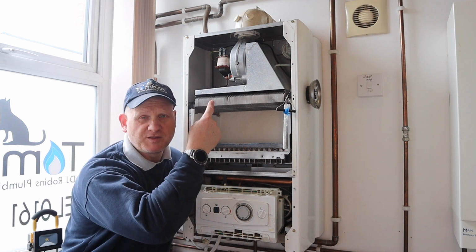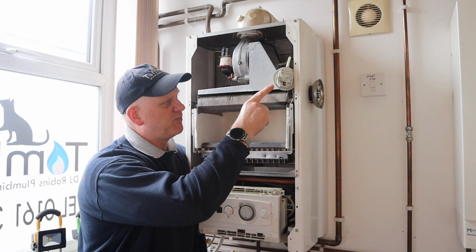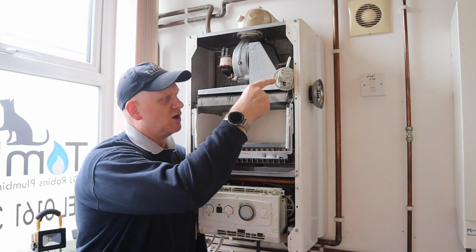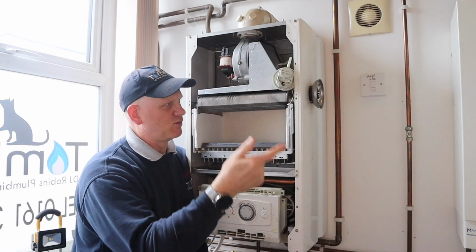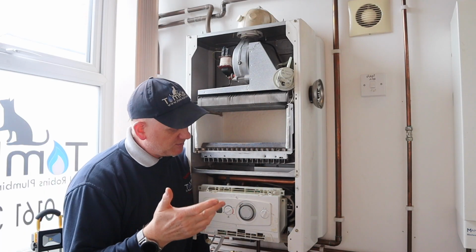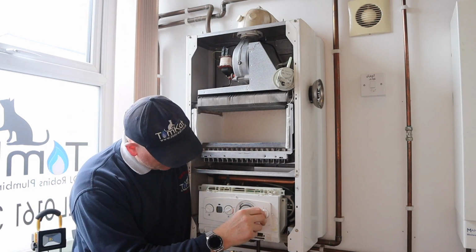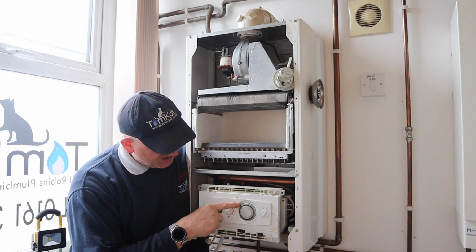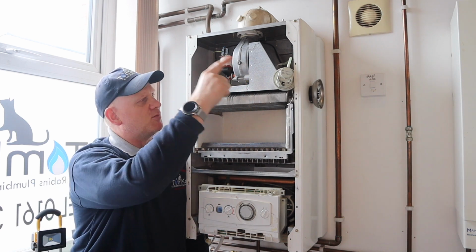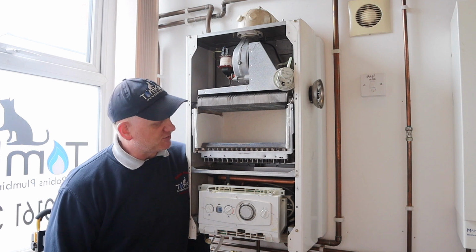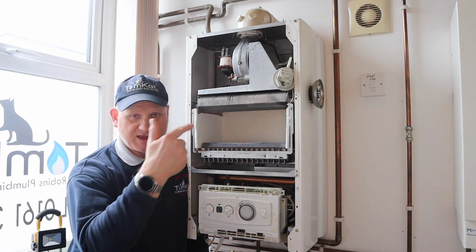So, let's see what other things we can do with the air pressure switch then. Now, this time what I've done is I've plugged one of the cables onto the air pressure switch. Now, the cables are actually the same colour, so it technically doesn't matter which way round these 2 wires go. So again, we need to turn it on. I'm not calling for any heat. Again, it's going to go through the purge. Again, you could hear the fans come on and it made the air pressure switch. Okay, and you can hear the air pressure switch knock out.